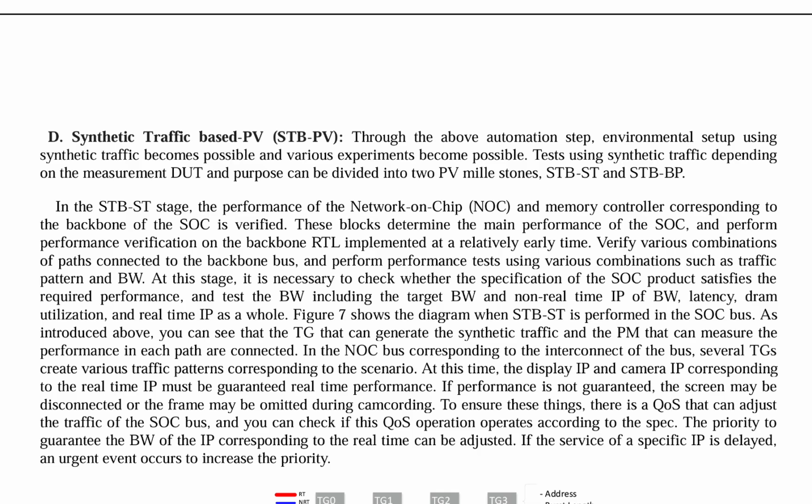These blocks determine the main performance of the SOC, and we perform performance verification on the backbone RTL implemented at a relatively early time. Verify various combinations of the paths connected to the backbone bus and perform performance tests using various combinations such as traffic pattern and bandwidth.